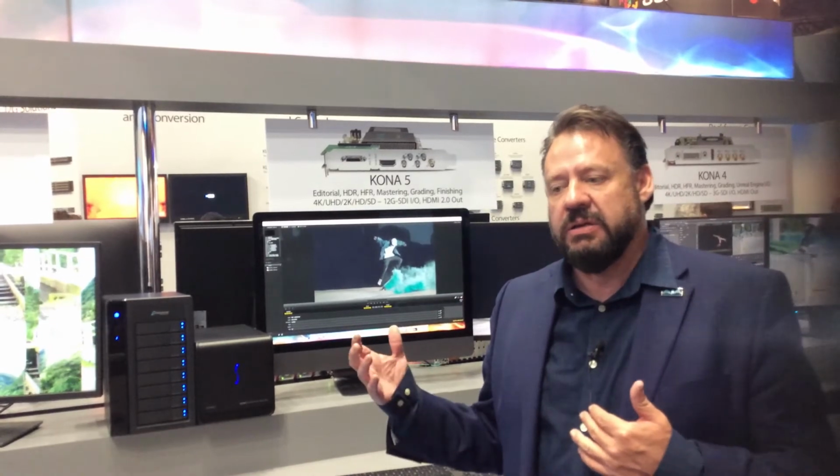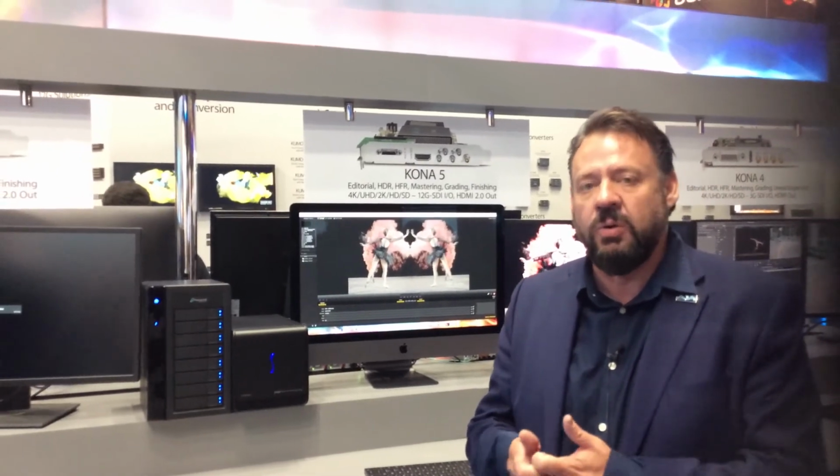And the FS-HDR, which we brought out about a year ago now, does real-time dynamic range and wide color gamut transformations. So with the latest version for IBC, version 2.6, we've added 4 more HLG LUTs from BBC. We have new outputs from the Colorfront engine, including ARRI Log C. And what's really going to be exciting for you is you can load your own 3D LUTs now. So you can load and save and recall up to 10 3D LUTs. This is a lot of flexibility in that product.